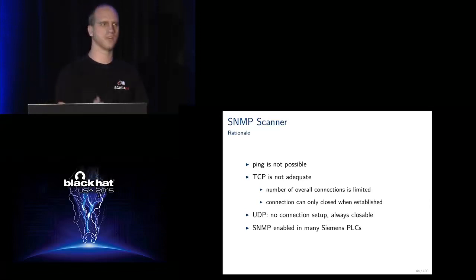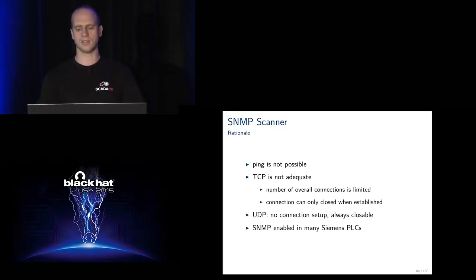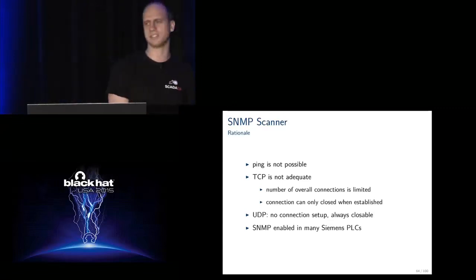So at first I try to connect to IP1 and it's not there. Then I still have seven further connections. I try to connect to IP2 and it's not there, okay, then that one also stays busy. So this means I can only scan up to 8 missing IPs and then it's busy and you cannot close the connection. So it's a very stupid design from Siemens, but it protects Siemens PLCs from being used as a TCP scanner, you know?